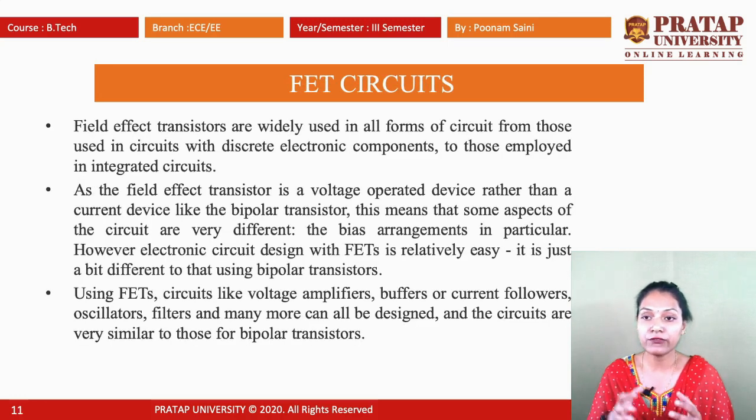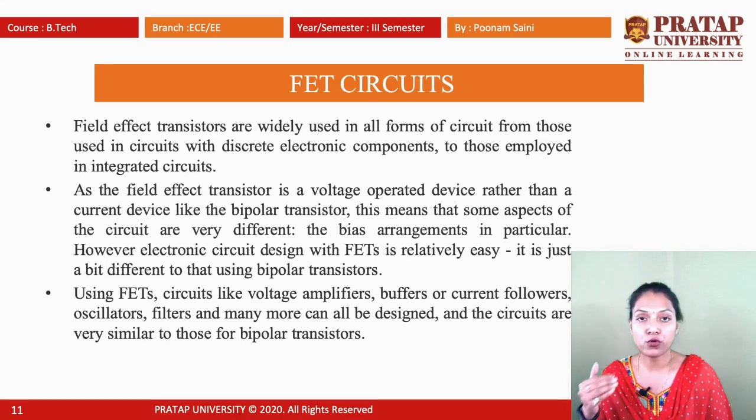Field effect transistors are widely used in all forms of circuit, from those used in circuits with discrete electronic components to those employed in integrated circuits. As the field effect transistor is a voltage operated device rather than a current device like a bipolar transistor, some aspects of the circuit are very different, the bias arrangement in particular.